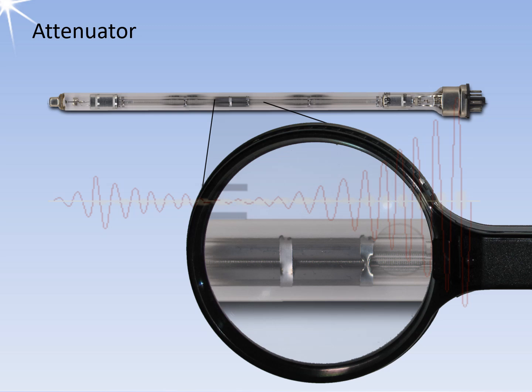This process reduces the oscillation on the helix to nearly zero, allowing all input energy to be transferred to the electron beam. Common forms of attenuation include coating the support rods of the helix with a lossy material or using a helix made of a conductor with a higher specific resistance. The transitions must be gradual to avoid reflections caused by the change in impedance.